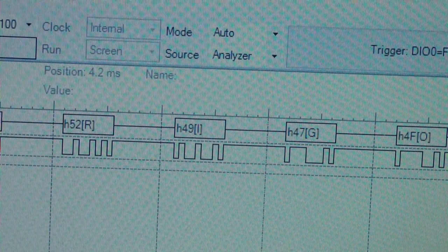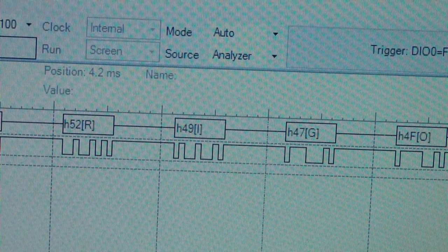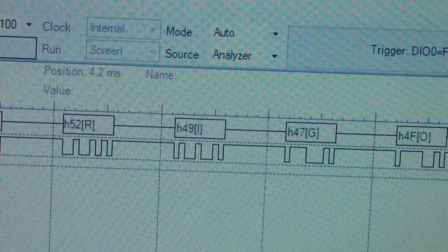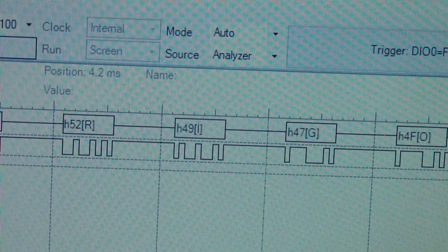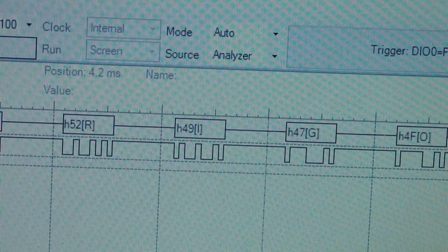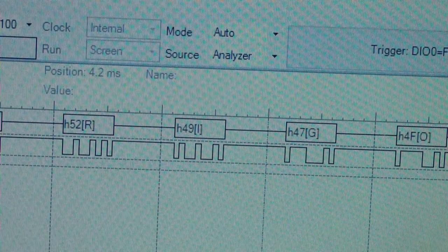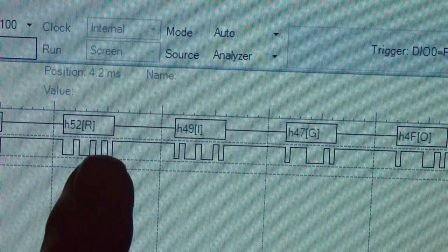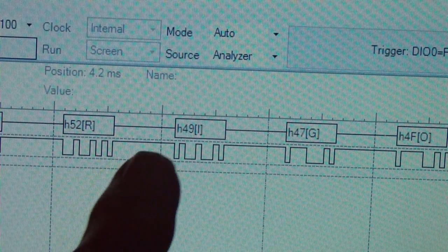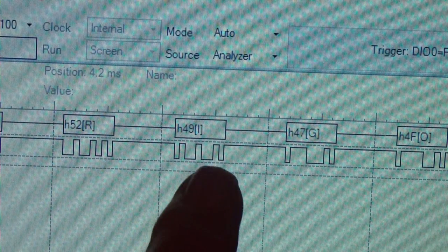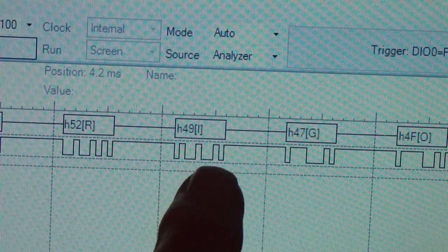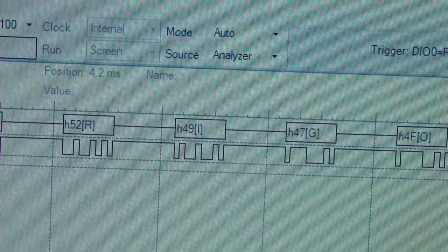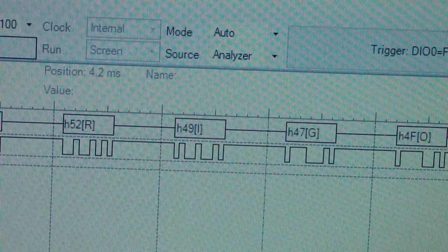The important point to make here is that, in my opinion, the Analog Discovery does a far better job of decoding a serial bus than the Siglent, in large part because it does a full ASCII decode. That is, it not only gives you the hex values, but it also gives you a display of the signal itself and decodes that hex value into the ASCII equivalent.